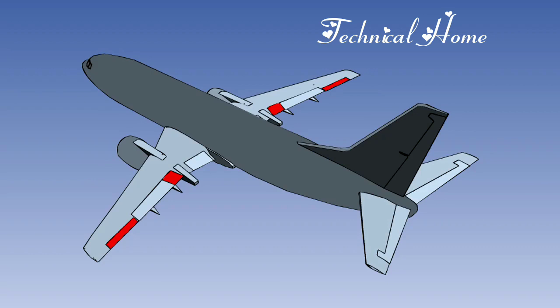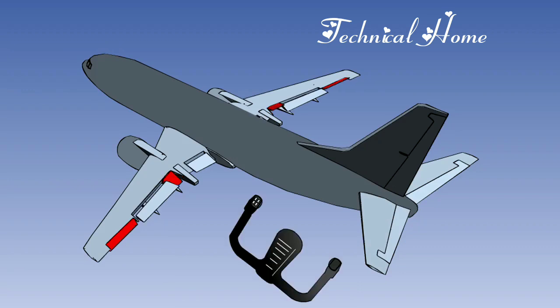Alternatively, two sets of ailerons are often fitted, one set at the wingtip for use at low speeds when the forces involved are low, and one set inboard for use at high speeds when the forces are greater and could cause greater structural distortion. On some aircraft, with both inboard and outboard ailerons, both sets are used at low speed.